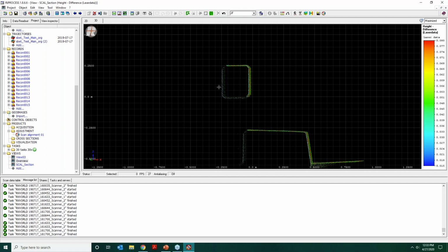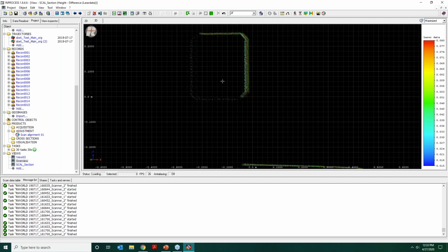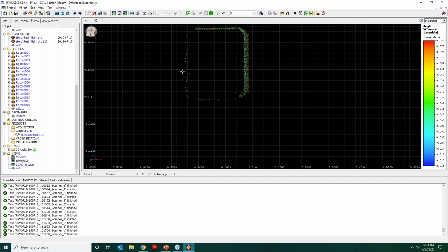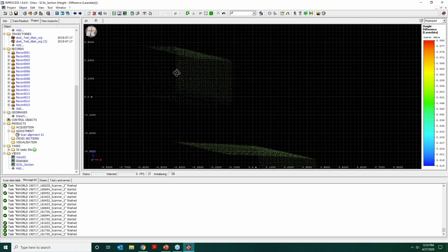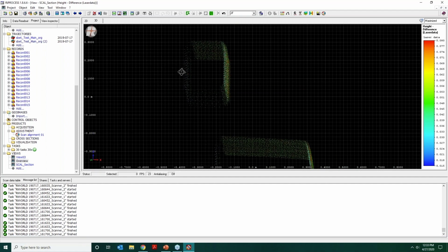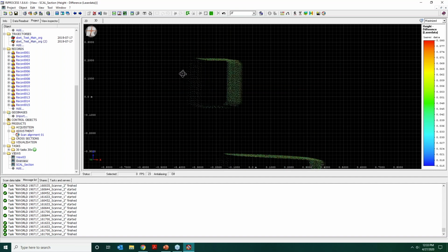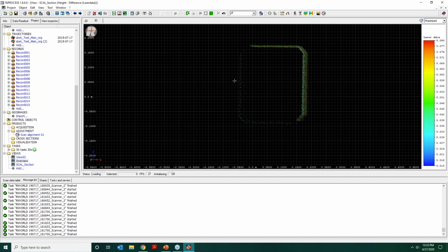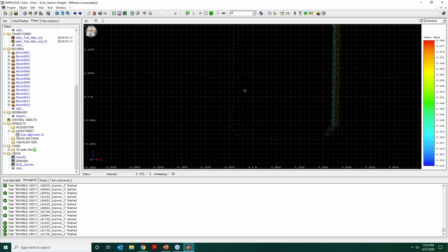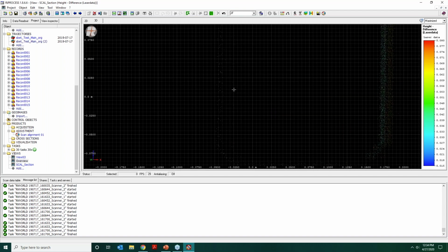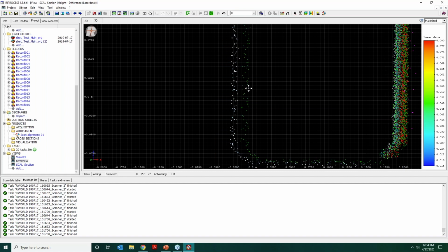And we can make some measurements. It looks like perhaps here there's some deviation on the outside. I'm not sure if the point density, the point spacing is in a way, as you can see here, that they don't quite line up with each other. And it's concrete, so it's not perfectly level. So maybe on the outside, these two records, as you're going underneath the bridge, aren't perfectly aligned on the back side of that as comparatively to the much denser points on the inside of the bridge.